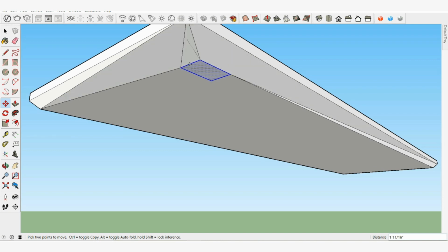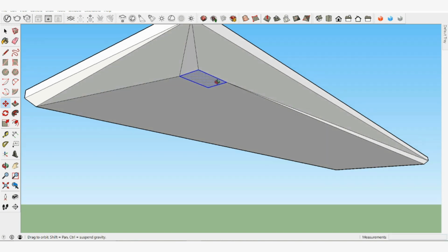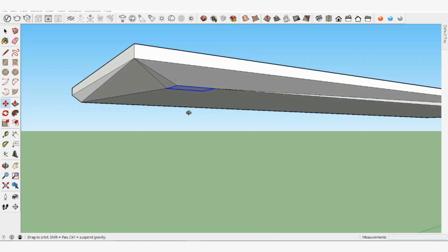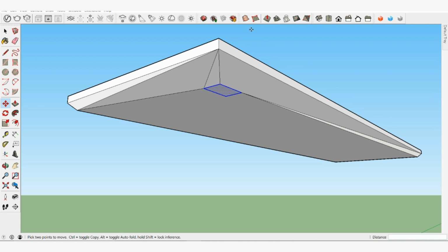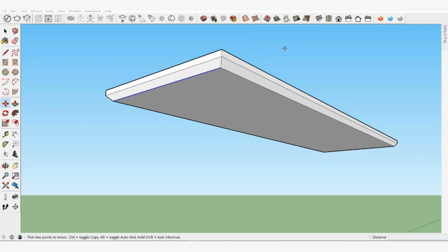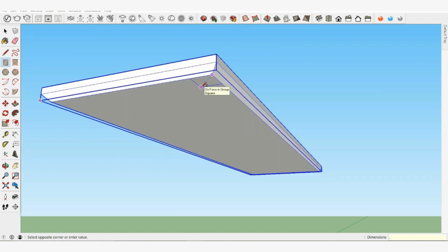This is one of the primary uses of groups, which will isolate our geometry, preventing the edges from merging. To see this in action, undo the rectangle using Ctrl+Z on a PC or Command+Z on a Mac. Then triple click to select the whole tabletop. Right or context click on the top and from the submenu choose Make Group. A new bounding box is shown around the whole top and it now behaves as a single unique entity.